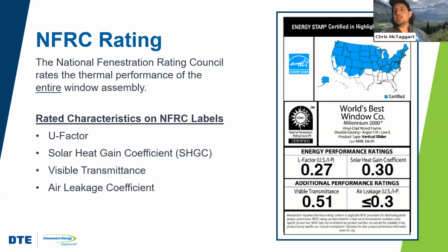There is more to it ultimately than just the NFRC values, but it's important to understand them because they help illustrate what you may be getting, and you can compare apples to apples from a performance value. NFRC is the National Fenestration Rating Council. This is a third-party body that rates windows and fenestration products for their performance values.